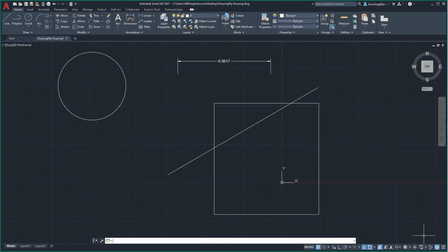The next icon moving to the right is Isolate Objects, a duplication of the Isolate Objects tool we visited earlier in the right-click contextual menu. In review, as a drawing develops and more objects occupy the workspace, this tool allows the user to temporarily isolate or separate out singular or a select group of objects to make modifying them visually easier.